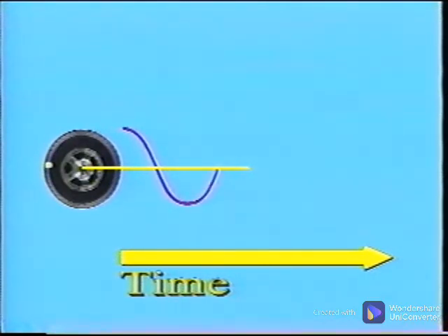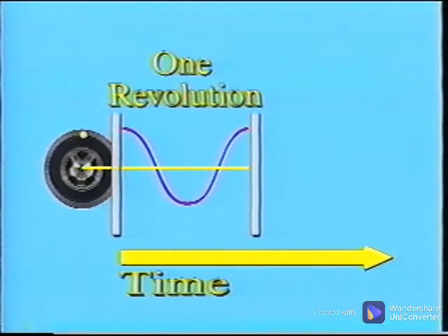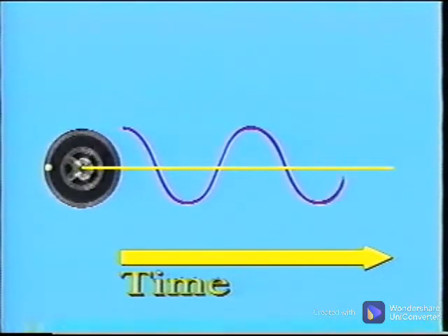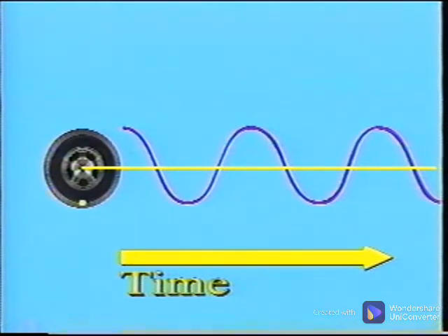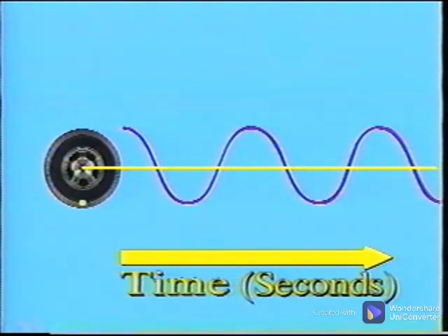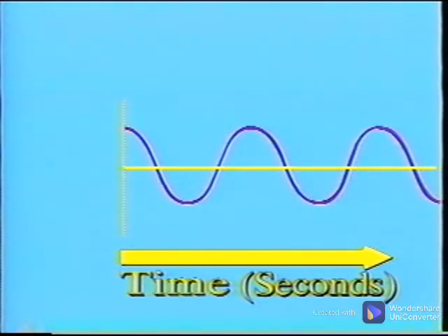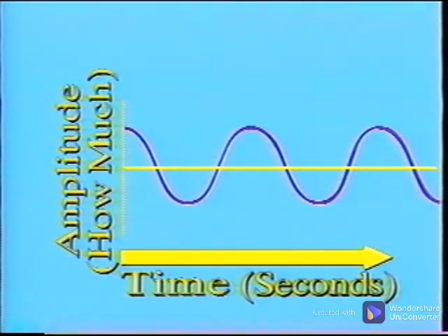The trace of the unbalance has now moved up to the center line of the tire, but is still to the right. The tire completes one revolution so that the unbalanced weight is at the top. This then is the trace of the path the unbalanced weight makes during one full rotation of the tire. As the tire continues rolling down the road, the trace repeats the pattern for each revolution or cycle. The horizontal or x-axis shows the time it takes to complete one cycle or revolution. The y-axis shows the amplitude or how much the unbalance moves during each rotation.